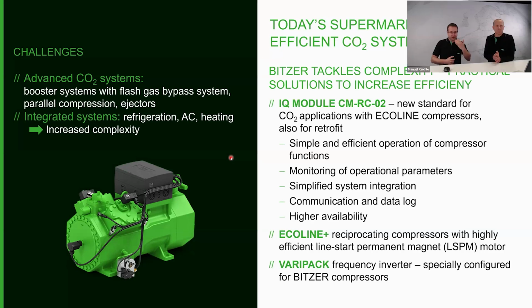Going back to the presentation, you said it, the system gets a little bit more complex by parallel compression, ejectors and so on, but also the integrated systems where you do refrigeration, air conditioning and heating in one system bring additional complexity. The target of Bitzer, or how we tackle these solutions, is that we brought our IQ modules. A lot of things which are complicated to run safely around the compressor, we put these operating functions into our IQ module. For the rack controller, it is the same interface as to a frequency inverter.